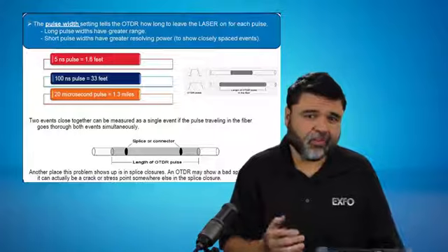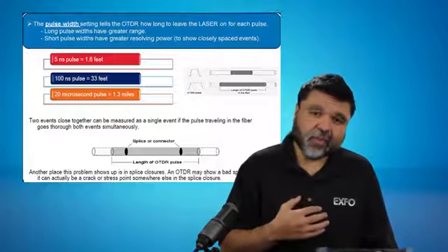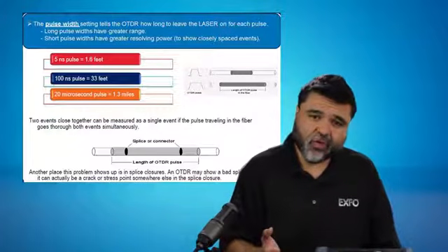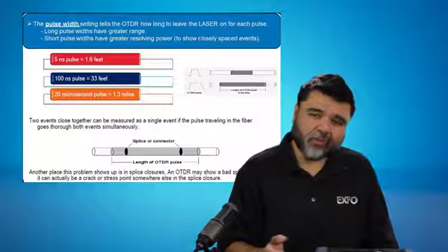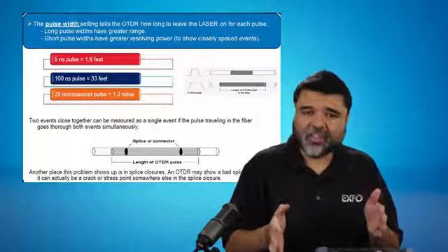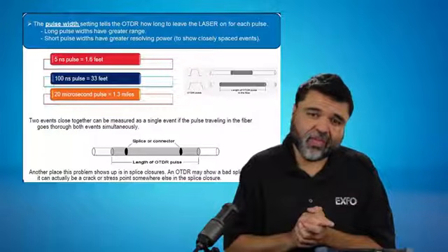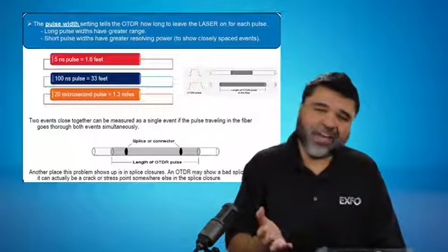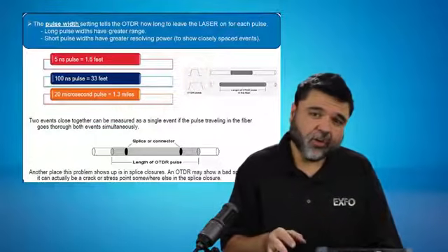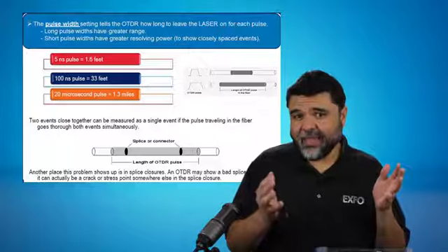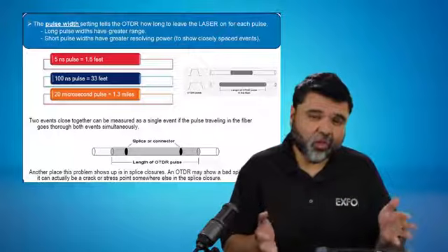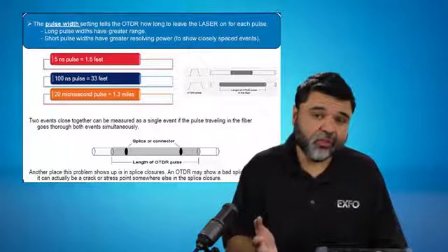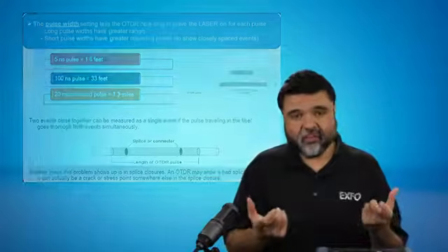And so to kind of put this into light, when I was a splicer or worked in disaster recovery, it wasn't too uncommon for us to have to use a patch or a throw cable to splice a damage. So if we had an auger that damaged our cable, we would come in with a fairly short throw cable, say 10, 20, 30 meters long, with splices on the end of that.